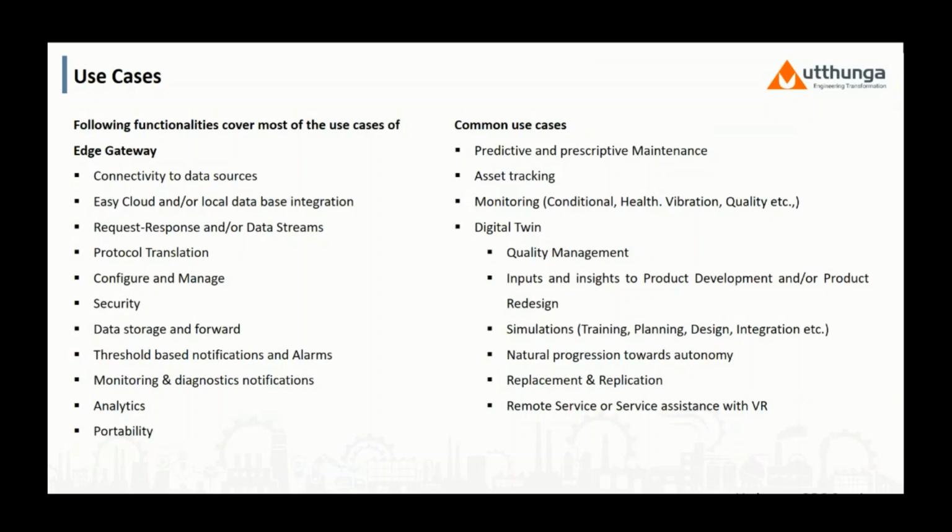And then protocol translation. On the northbound, it can connect to any different protocols, and that can include other OPC servers or older OPC DA classic servers as well. So it can connect to different devices with their protocols, aggregate the data and expose the data as OPC UA data.